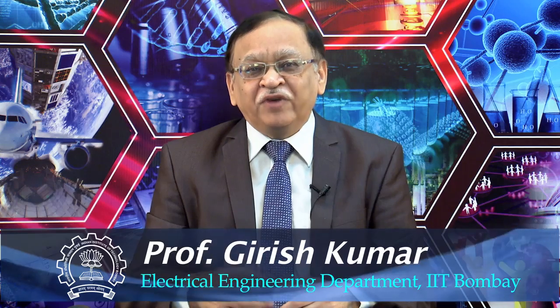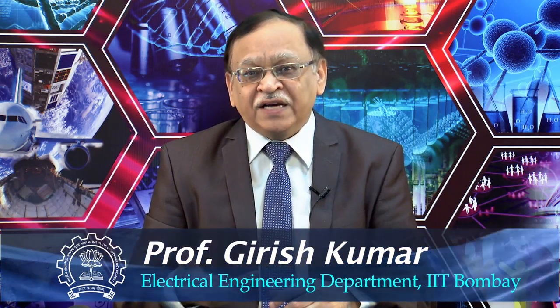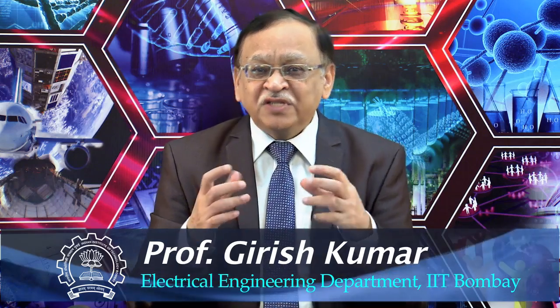Hello. In the last few lectures, we have been talking about microwave amplifiers. To design a microwave amplifier using either a transistor or even an IC amplifier, you must first see what the S parameters are at the desired frequency and what the biasing conditions are. After that, you find out the value of delta and K, so that you know whether the amplifier is stable or not at that particular frequency.